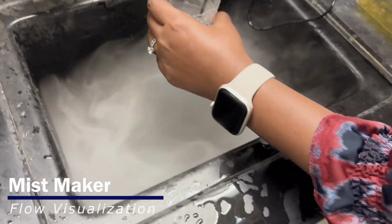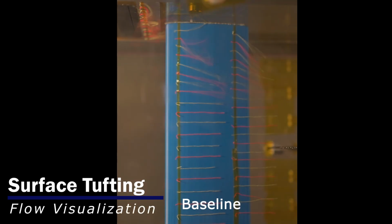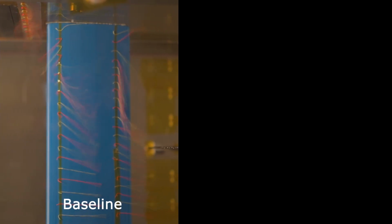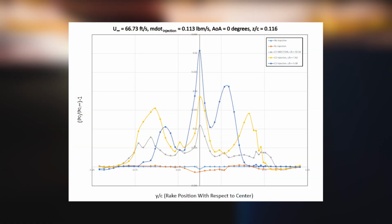As part of our requirements, we implemented flow viz techniques to understand how the leakage air was interacting with the main flow along the stator and injection surfaces. Our first technique, known as surface tufting, can be seen here. The baseline injector case shows chaotic and turbulent behavior as the leakage air impinges the main flow. COANDA Surface 3 causes the flow to remain straight and attached around the stator, which is a product of fluid entrainment.